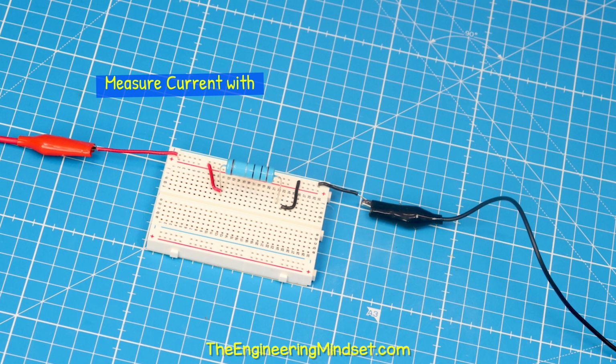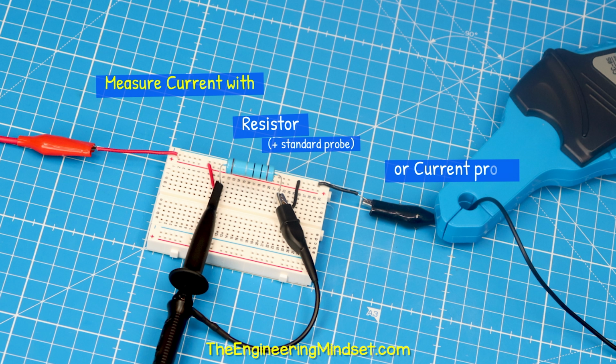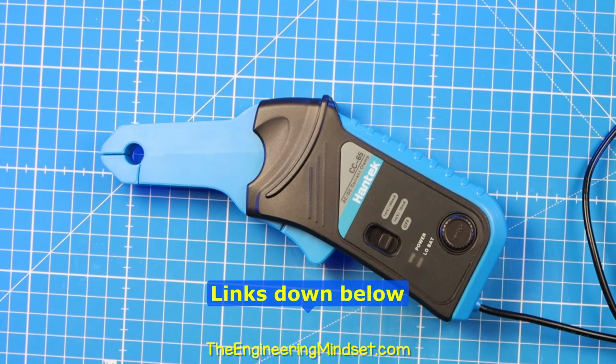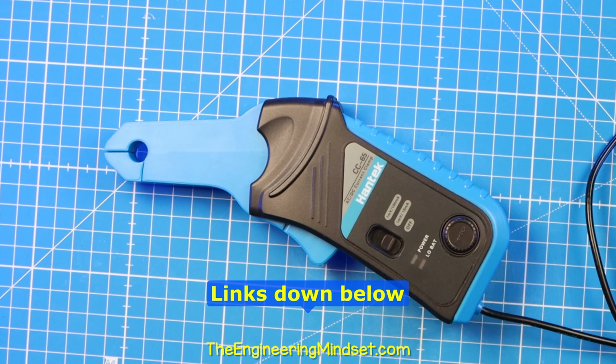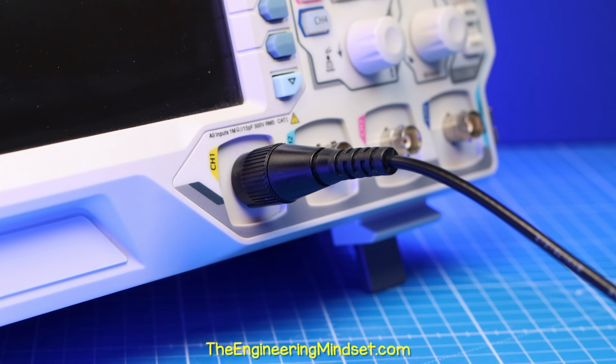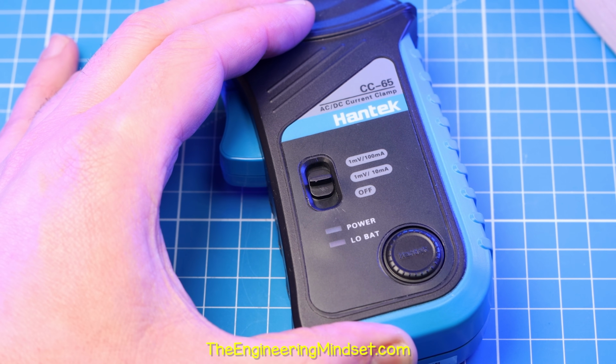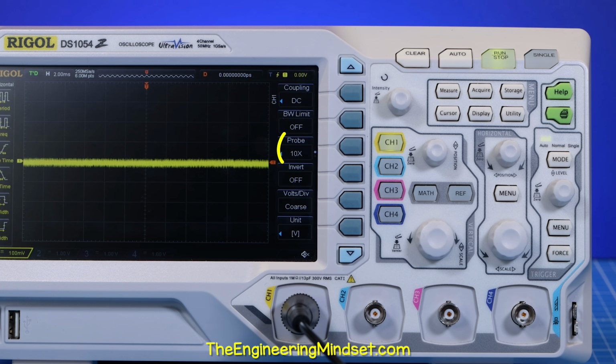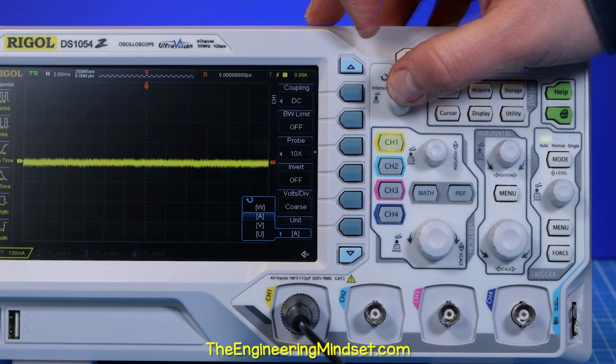We can measure current using a resistor or a current probe. I'm using this entry-level clamp probe, and I'll leave a link for you in the description if you're interested. Connect it to the oscilloscope, then select the 1 mV per 10 milliamp setting. Check the 10x is selected on the channel options. Then change the unit to amps.